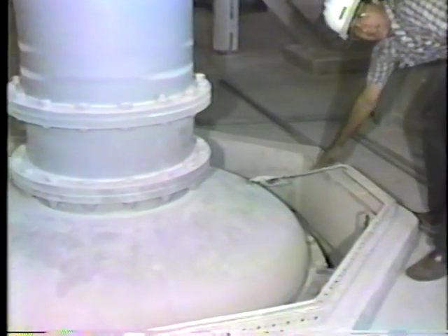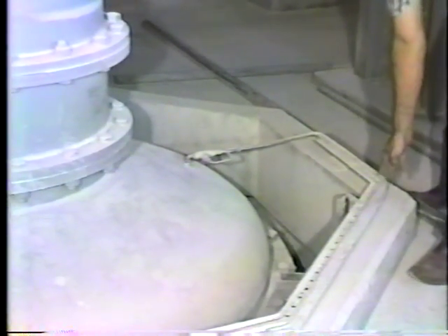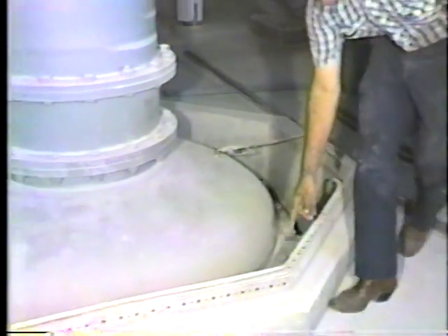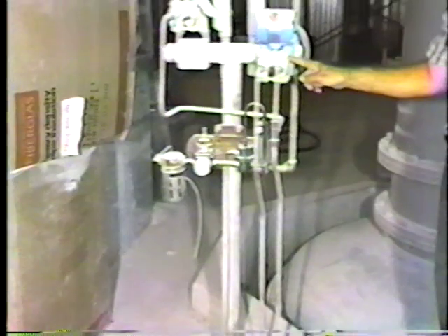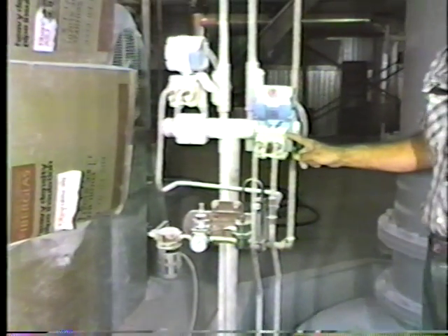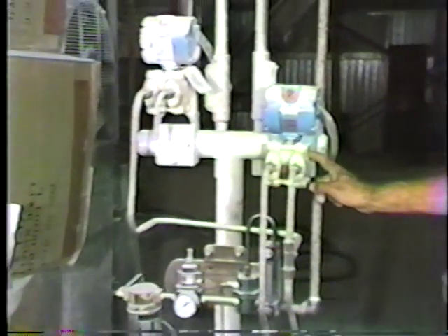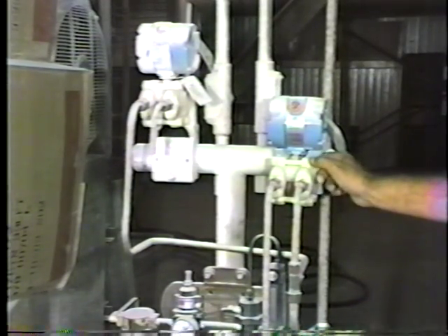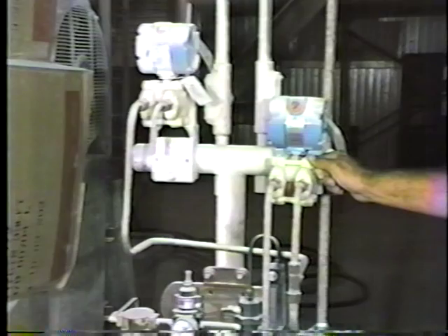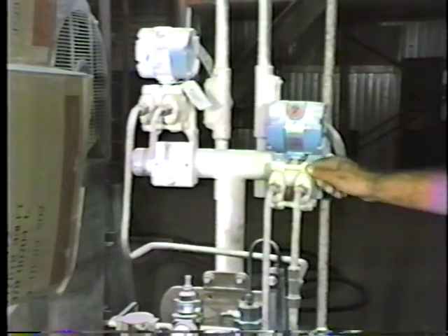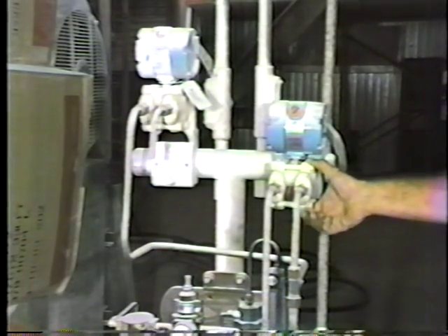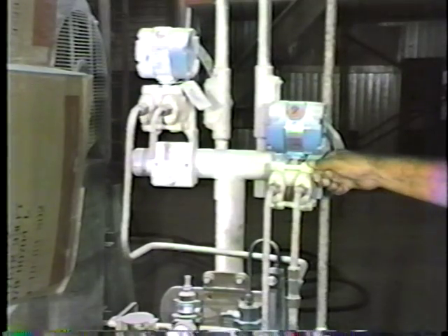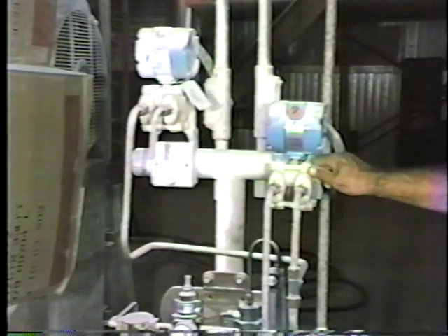This is the lower pressure side. Up over is the pressure transmitter, which then sends a 4 to 20 milliamp signal to the computer. The computer, based upon mill speed, computes a differential pressure that we should be operating, and then in turn generates a signal to the Merrick feeder.